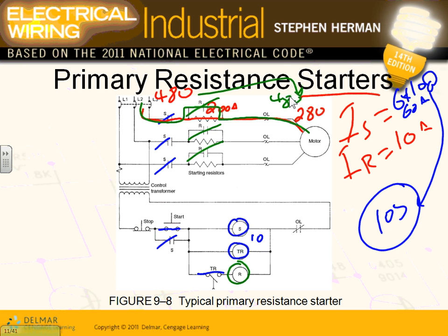Now with VFDs, you reduce the frequency and the voltage. So that's one method of reducing inrush. Who cares? Remember that 60 amps now? If I do it this way, I can cut this one almost to 30 amps inrush. That's better than 60. One progress.